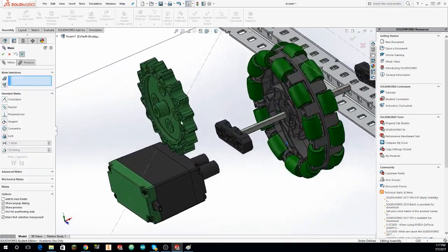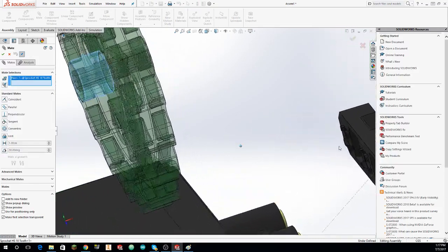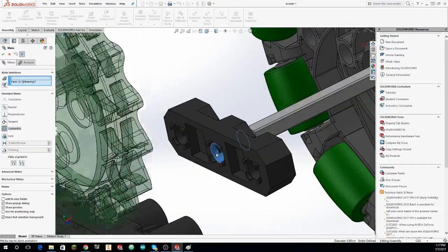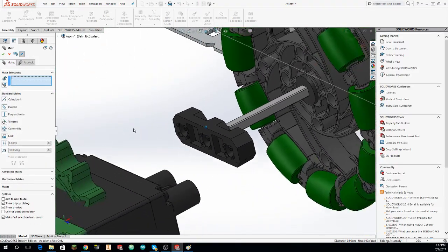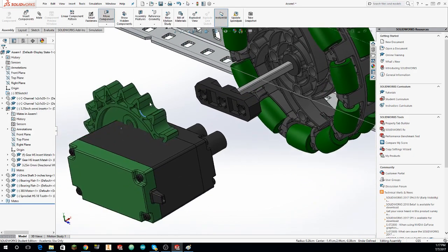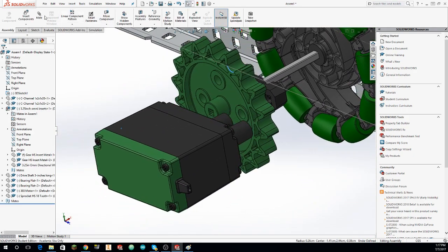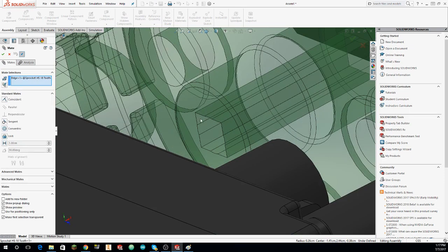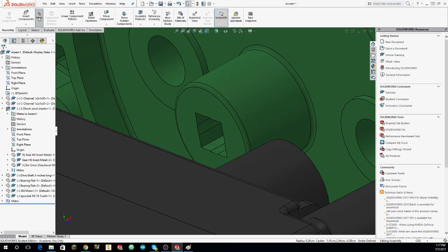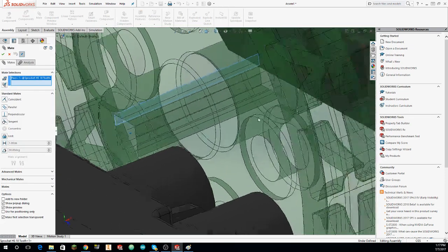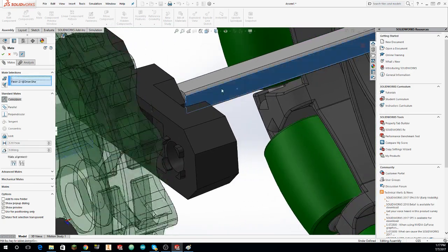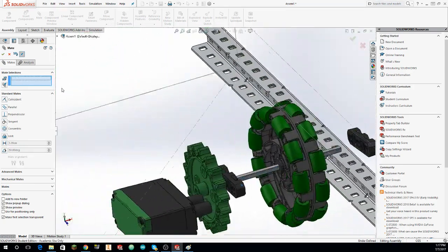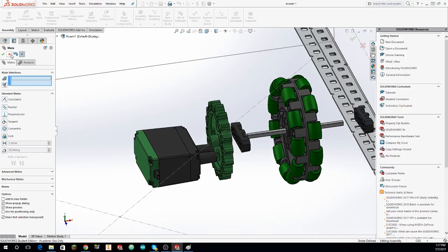So, we're having a sprocket here because we want to have all 3 of the wheels connected together so that way the power gets transferred in between them. Like if only one of them is being sort of stalled, then it'll actually draw power from all 3 of them instead of just one motor and cause that one to burn out. So it's pretty obvious stuff, but some few people might know that.